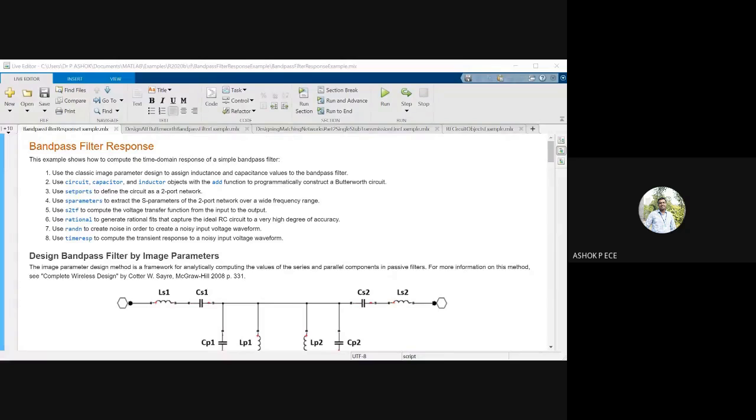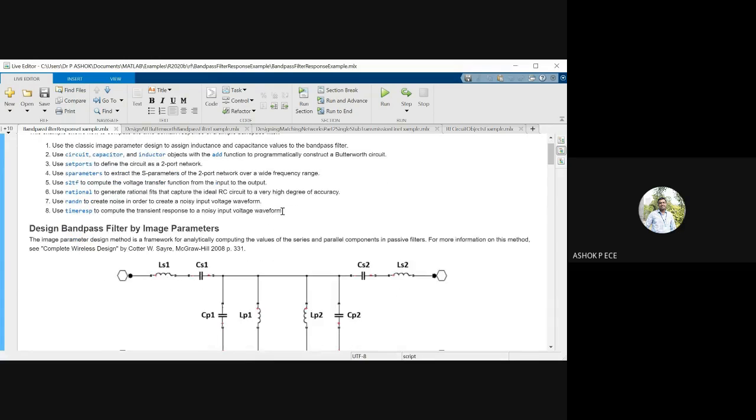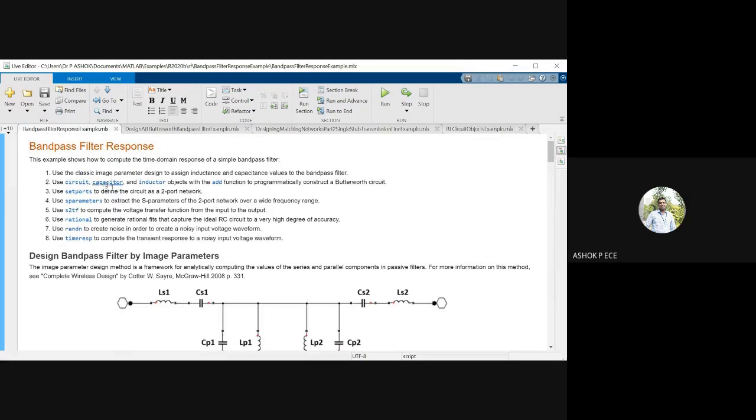If you want even more detail, I can give an example of an FM receiver. An FM receiver can receive all the FM station signals. But when you are tuned to a particular frequency, it can filter out that particular frequency alone. Correct? So that application can be thought of for this band pass filter. It is going to allow a particular band of frequencies and reject the remaining band of frequencies. I'm going to use capacitor and inductor only for designing this band pass filter.